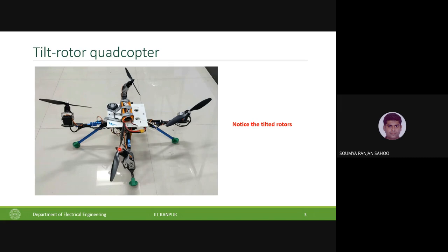Okay, so you would have a camera, let's say, installed. So in such a case, what would happen? When you move in any direction, a conventional quad encounters roll and pitch again, so you're not looking vertically down. What people would do in such cases is install gimbals to carry these cameras. Gimbals are a little costly as compared to the modification that we have done. So now, with this modification, you don't need the gimbals.